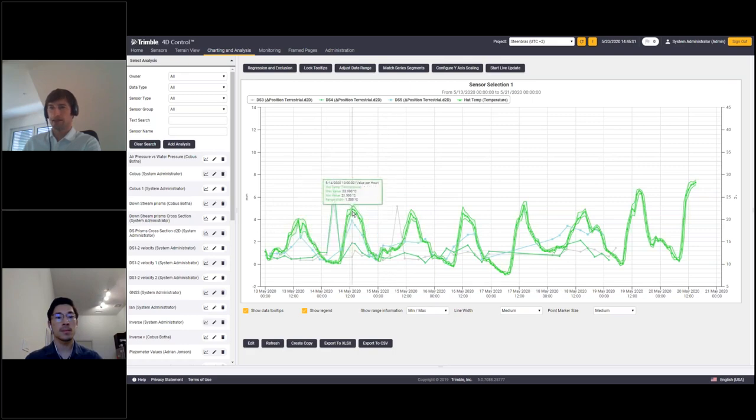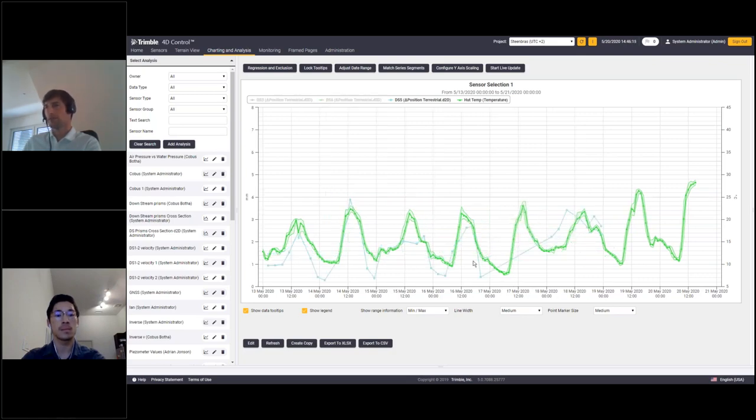There is really a spike. This is during the day. You see 12 p.m., and the lows here, so this is during the night. At the moment, it doesn't really say a lot. Let me maybe disable 2 of the 3 targets. And here you now nicely see, although there is not a lot of movement, we are really in the millimeter range here. We have a 2D displacement of my target DS5 up here, which really follows the temperature. So there is a nice way you can analyze data, and this is an example to demonstrate that the 2D displacement really correlates with the temperature change.